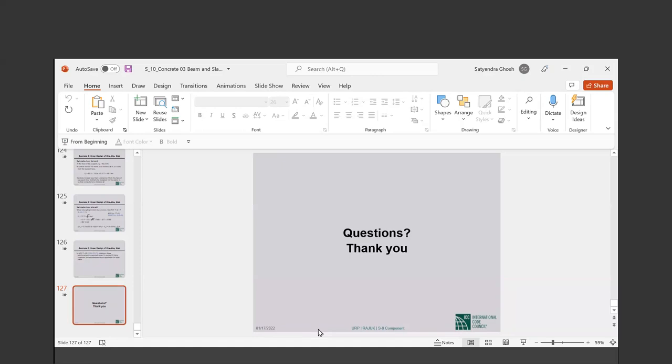Read that last sentence again. The diagonal shear rebar, horizontal and vertical shear rebar, and the flexure rebar all together create such a congestion that concrete pouring becomes difficult. Yes. I agree. So you have to be very mindful at the design stage. This is true in all situations, particularly high seismic design.